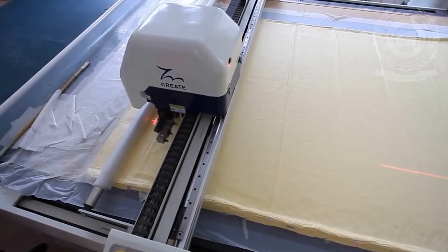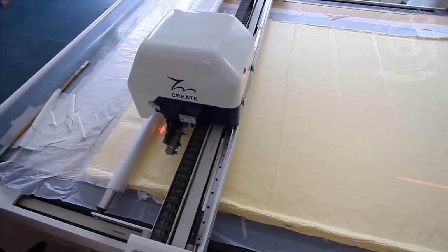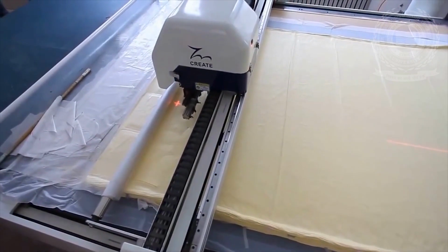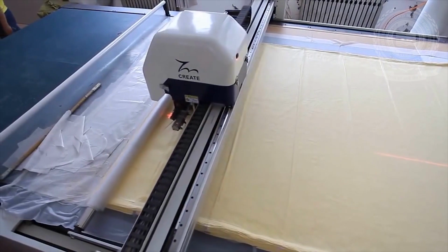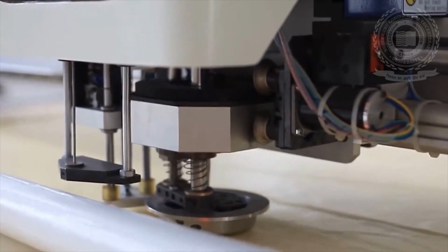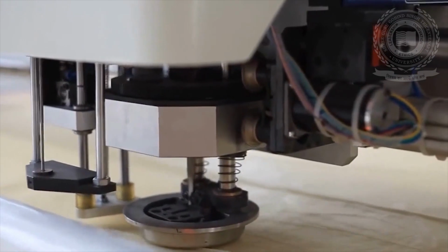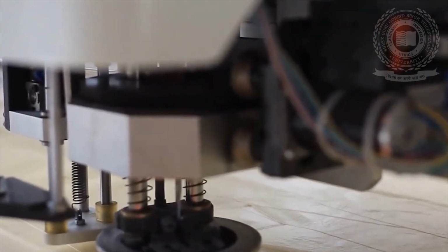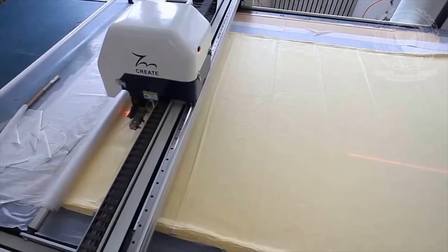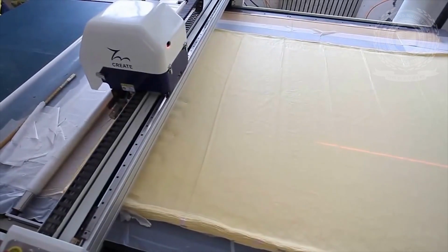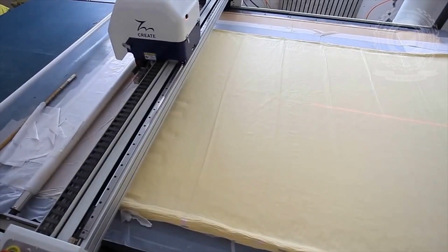Now you can see the working of the computerized fabric cutting machine, in which the cutting process is carried out by a circular blade which runs along the surface of the fabric according to the set commands previously fed into the computer. When the fabric cutting command is given through the computer, the cutting knife starts lay cutting from a reference point starting in the computer memory of the marker. Notch points are made by the same cutting knife.